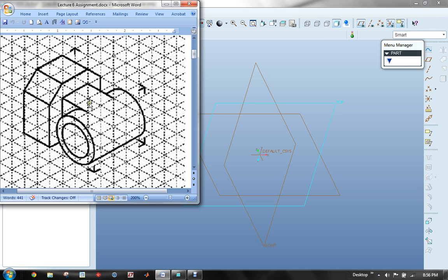And then there's this third feature, which starts at the back block and becomes tangent to the cylinder, and we're going to try to show how we make that tangent with the constraints. So the first thing we're going to do is create this back block, and we're also going to notice that it has a symmetry line here, so we're going to allow one plane to maintain that symmetry for us.